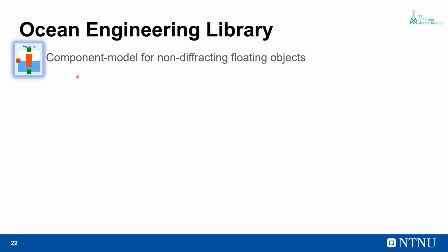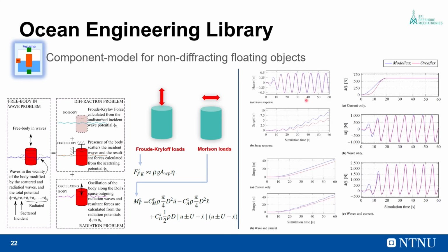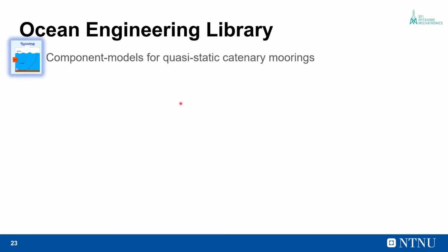In developing the component models for non-diffracting floating objects, which means that the object is relatively small compared to the wavelength, we use the simplifications that we described earlier, the Froude-Krylov load and the Morison load. And again, we compare our results with the results obtained using OrcaFlex, and we demonstrate satisfactory agreement.